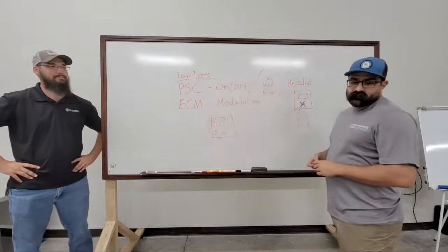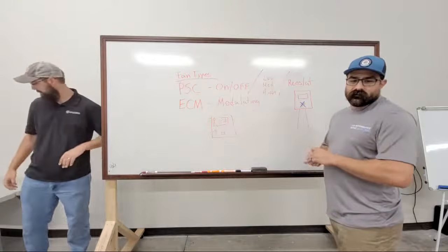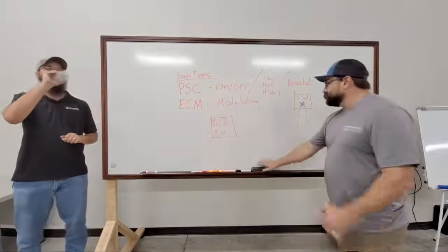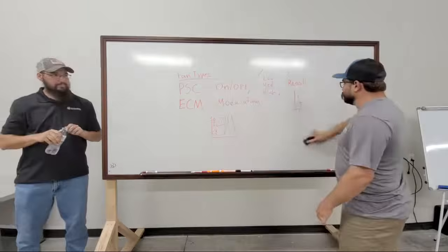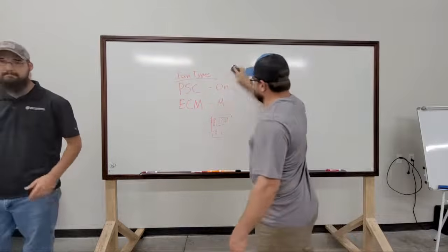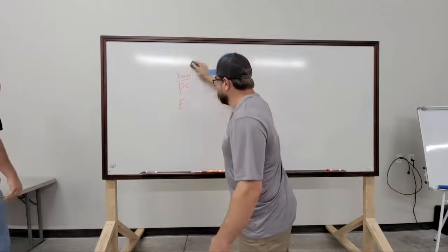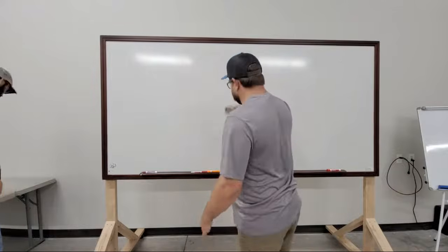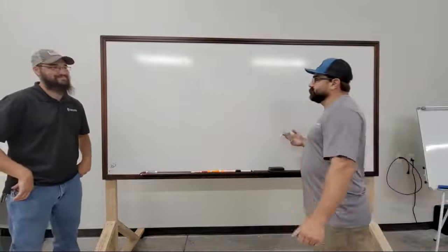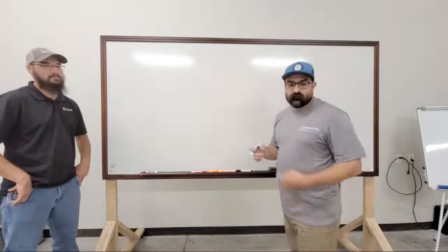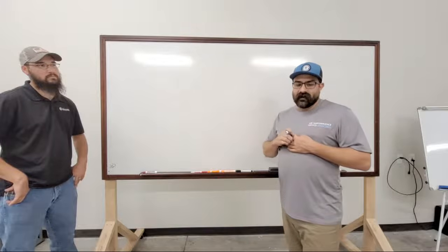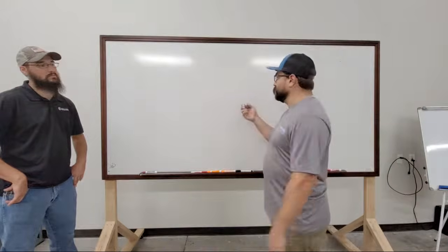That's fine. So let's see. That touches on fan speeds and types of fans. So I guess that will leapfrog us into heat on a terminal unit, or VAV box, or fan powered box, or fan terminal unit, or whatever you want to call it. There are two basic types of heat control in a VAV box.